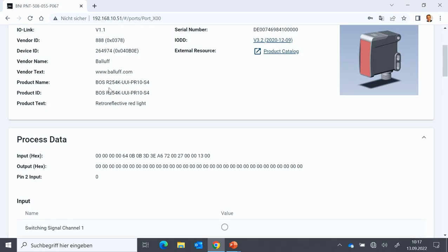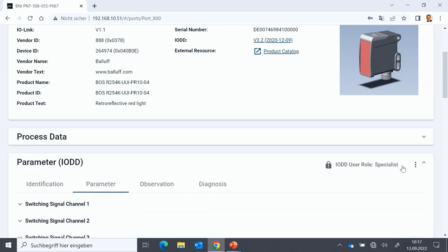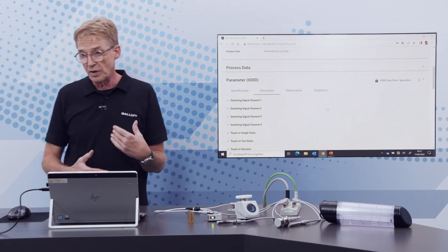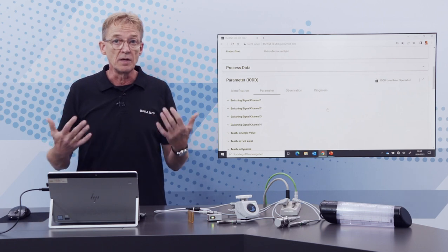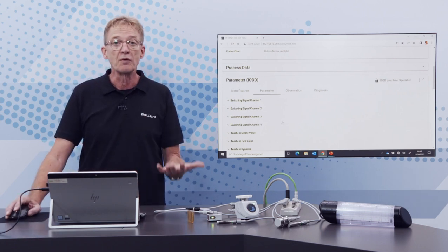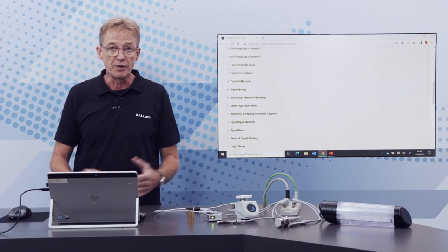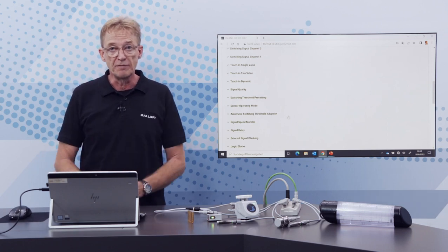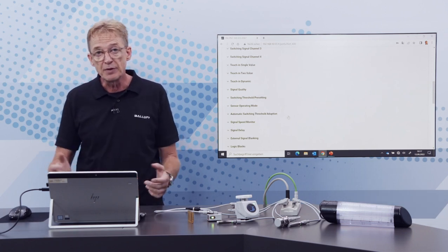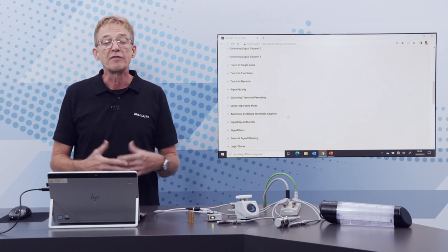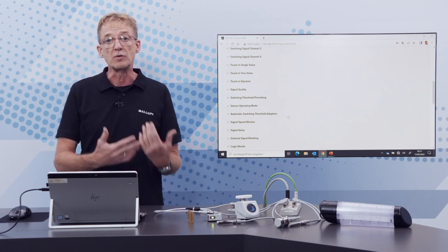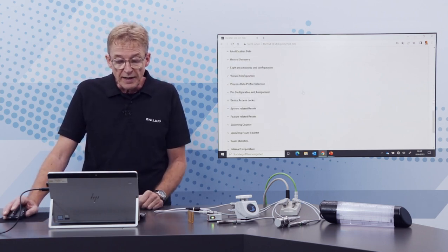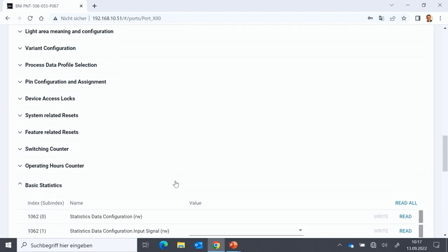Now we can create some basic statistics also directly in the smart automation and monitoring system devices, which will reduce the workload in the PLC, for example. Now, if you want to know over a specific time period, for example, what was the minimum and the maximum of the vibration in this specific time period or something like that, then we don't have to do that always in the PLC. We can do it directly in the device as well.